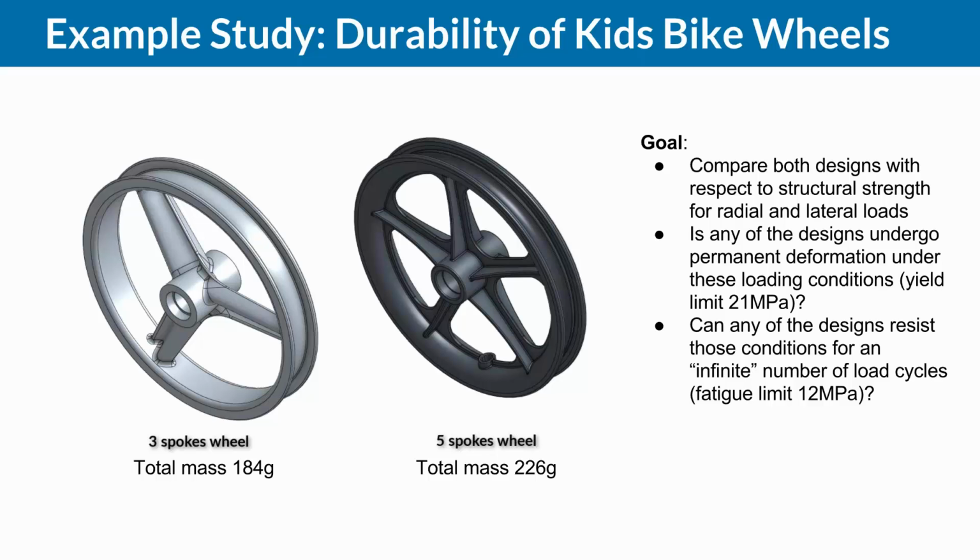This infinite number is of course not infinite. For most materials, it's about 1 million, 10 million, 5 million, 500 million, depending on who defines that. But it's a significant number of load cycles that even a bike wheel will not exceed.